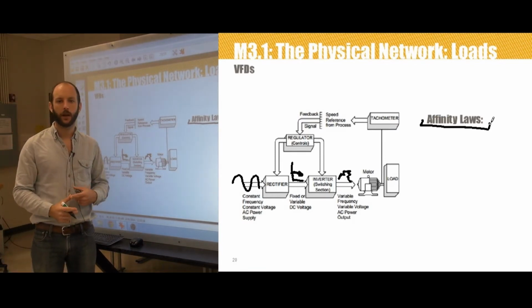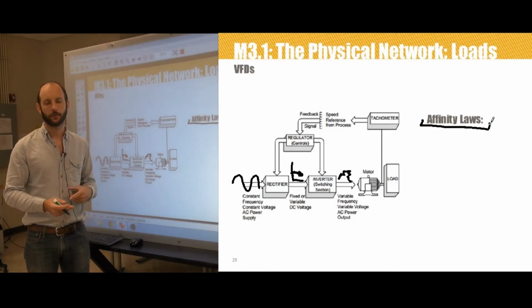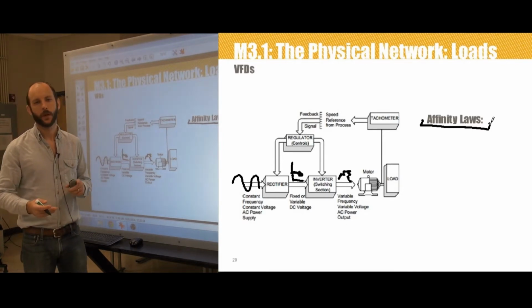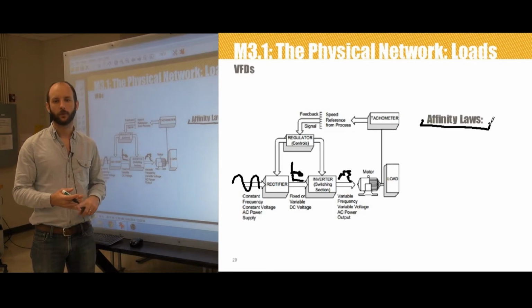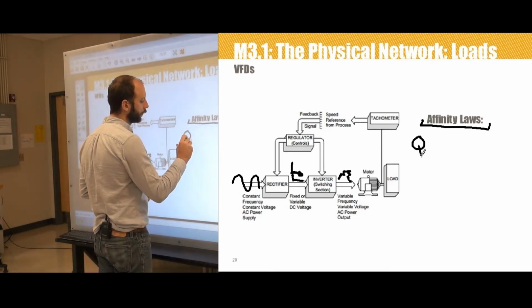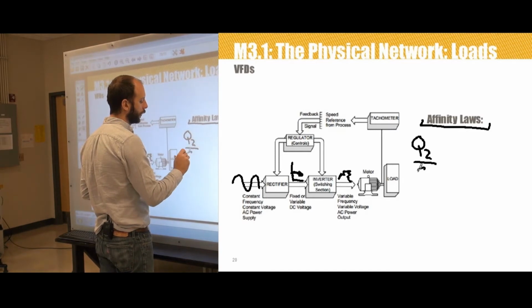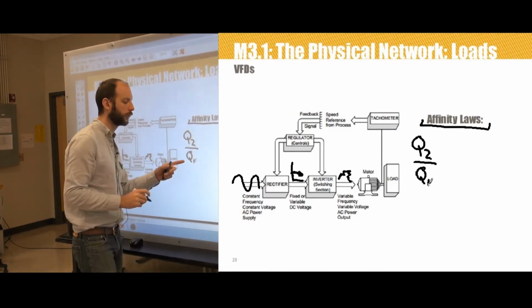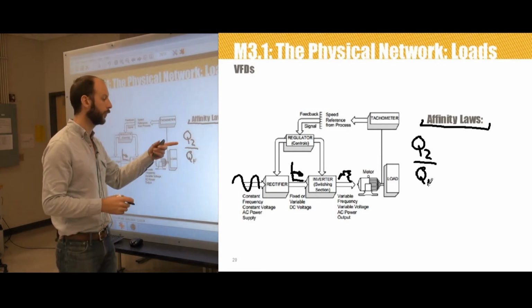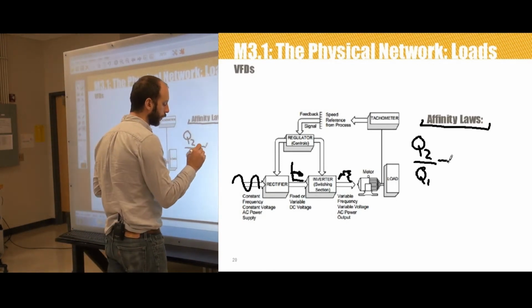These are commonly applied to pumps, fans, and hydraulic turbines. And we're going to just list the affinity laws for you. The first is that flow is directly proportional to speed, and the variable for flow in the affinity laws is Q. If you've taken thermodynamics, you recognize Q is often used as the heat flow. Well, in this case, we're just using Q as any sort of flow, typically water or some sort of gas.